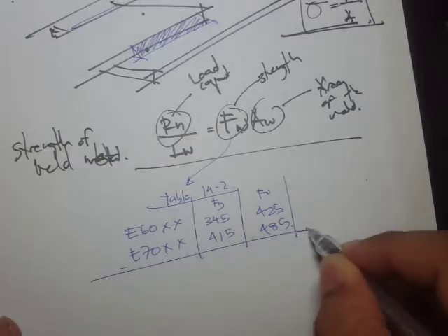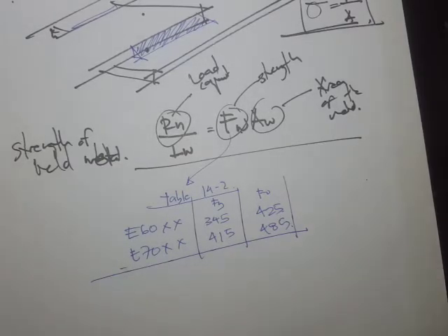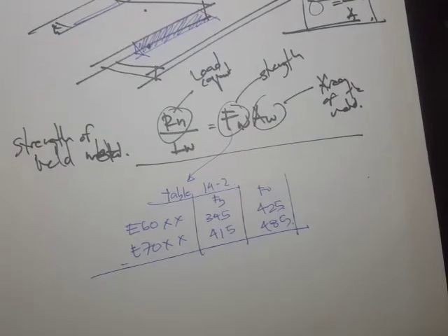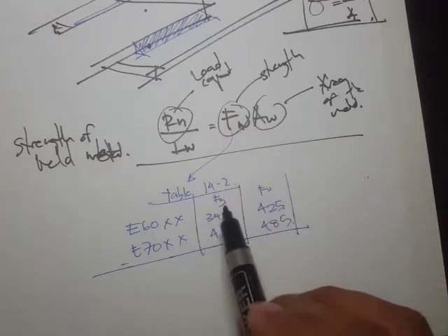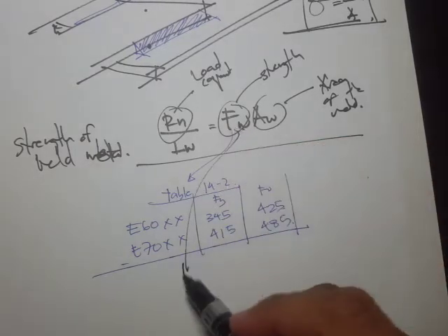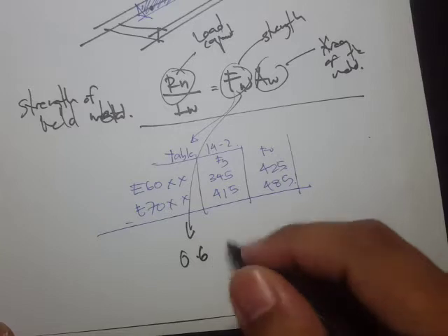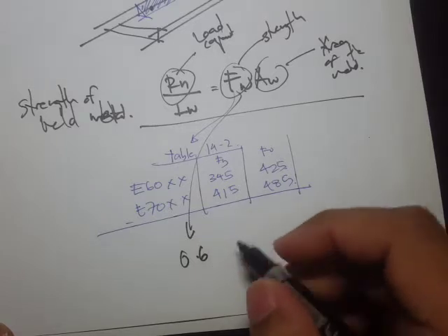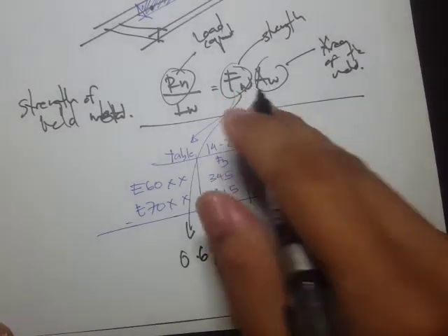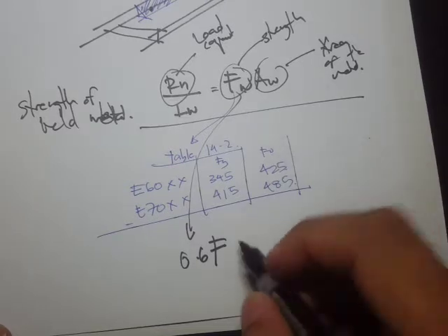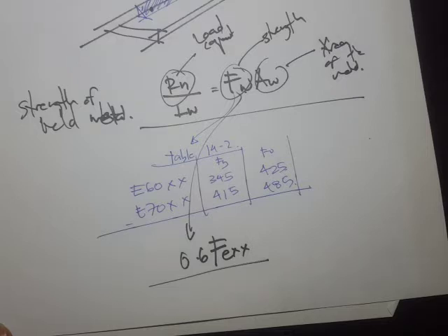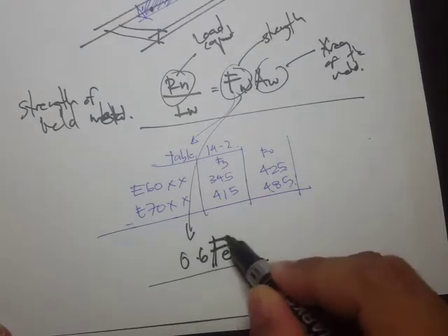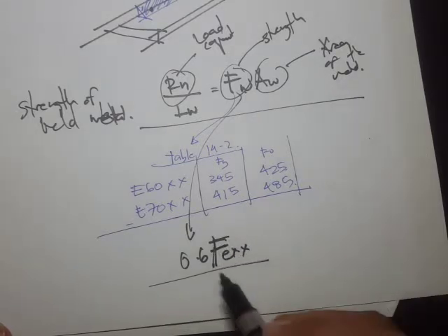Okay, so it's already tabulated, but we're actually taking the shear capacity. So it's not just the Fy, but rather this is the 0.6 Fy. Of course, we say Fy sometimes when we refer to the steel, but here let's just denote it as FEXX.